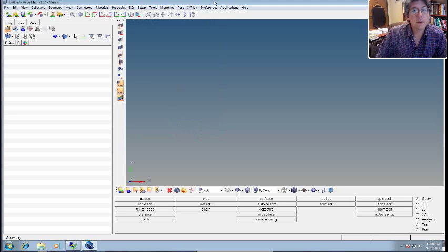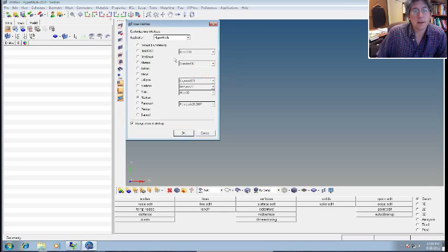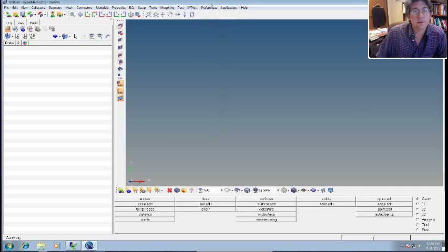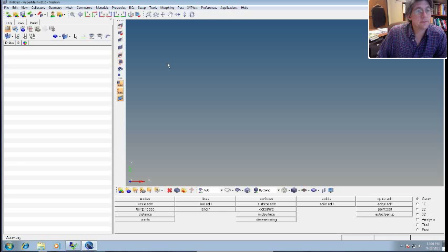All right, so up here, you can see that we're in the Nastran mode. That's the user preference. If I go back here to preference, I can see user profiles. That brings up that window again, so you can change it later on. If you have to import a file from Nastran to make it LS-DYNA, you can do that. If you do it later, that's under preferences, user profiles.